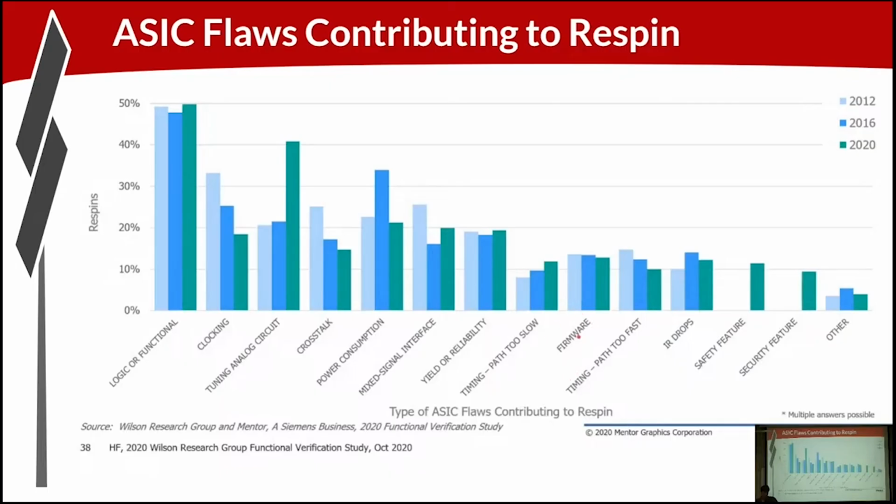software verification in all of this can be a significant effort on its own. I'm not really talking much about the software and co-simulation, co-verification of your software or firmware together with your hardware, but that's also a big topic. Yeah, so we've got timing paths that are too slow and timing paths that are too fast. Both can be problematic. IR drops, again, very physical in nature.